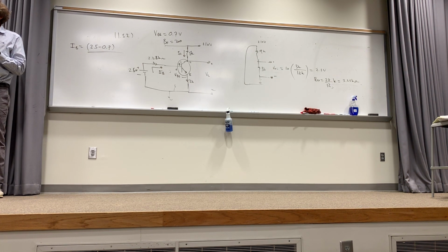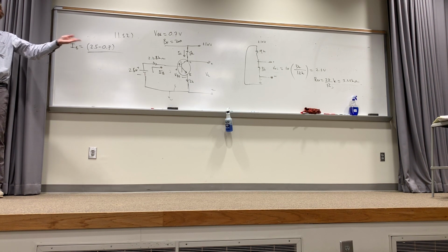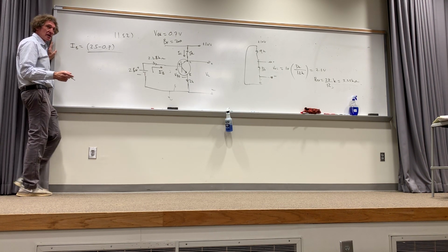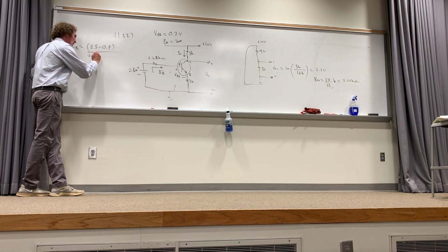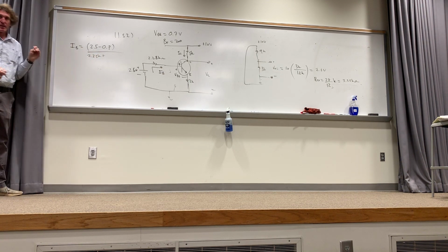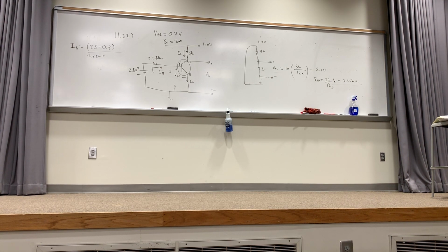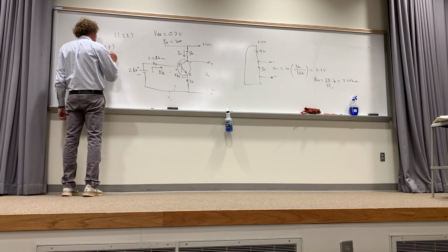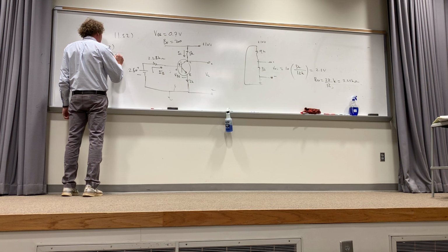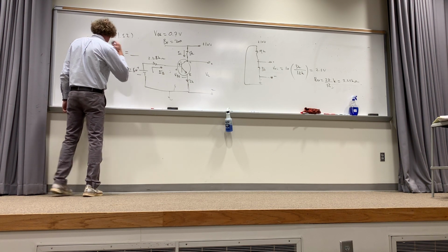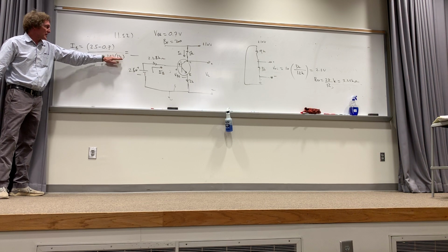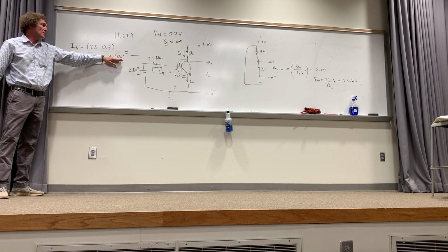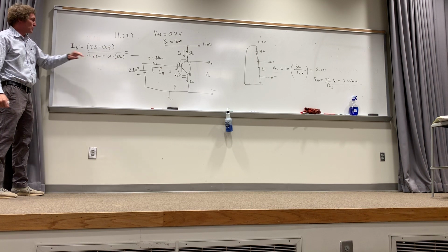But what's stopping it? Well, there's a resistor in the base circuit right off the bat that's 2.25K, correct, class? So that's 2.25K plus, what else is stopping it? 2K. 2K, but what do we have to multiply that by? Beta plus 1, right? Because it's going to be magnified. Everybody with me? So it's that plus beta plus 1, or 201. I would just put 200 times 2K. And you can see right off the bat that this is going to dominate the effects, right? The 201 times 2K, not the 2.25K.